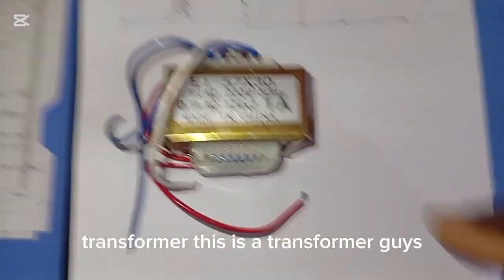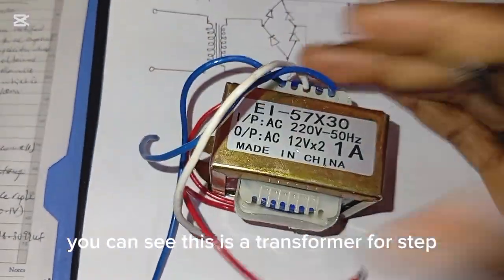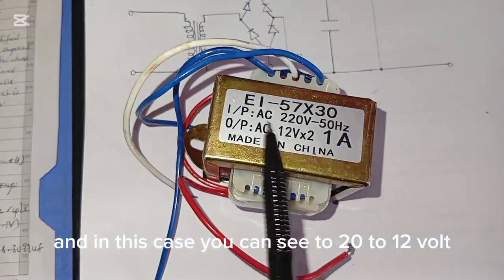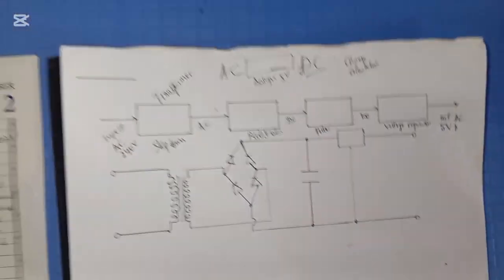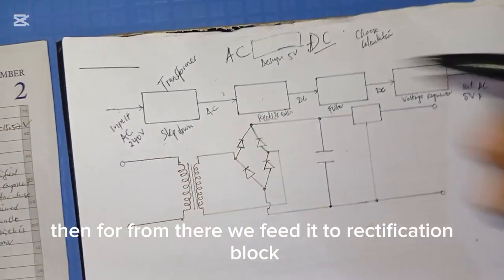This is a transformer, guys. You can see this is a transformer for stepping down the voltage to a manageable voltage, in this case to 12 volts. So we'll get 12 volts AC from this transformer. Then from there, we feed it to the rectification block.